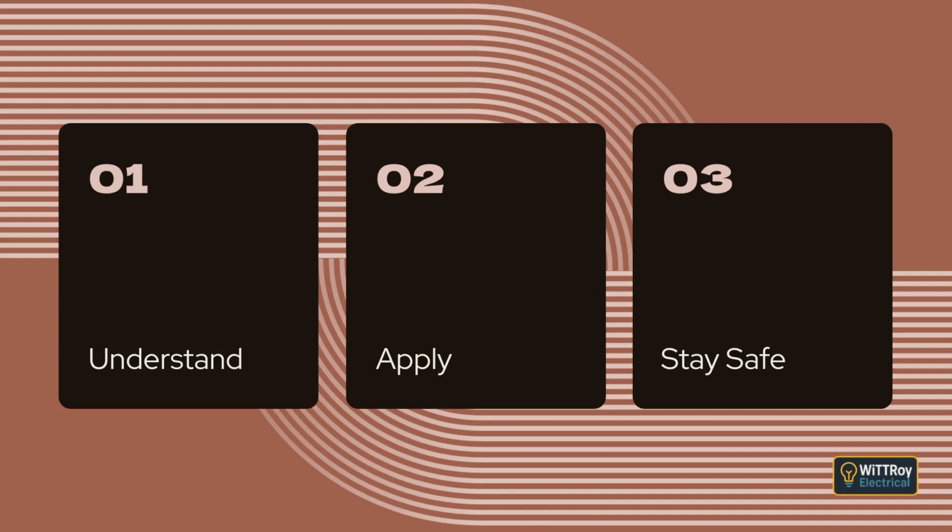When colors are used for identification, they must follow the colors listed in Table 3.4. Green, yellow, or the green and yellow combination must never be used as active or neutral conductors in installation wiring. These colors are reserved for earthing and equipotential bonding only.